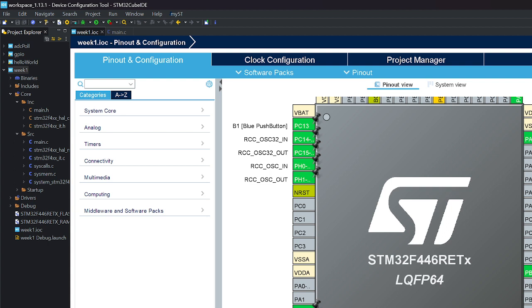One of the nice things about naming them is that in your code you reference them by the port, red LED GPIO port or red LED pin or what have you. Then if you need to change them around, it just changes the defines in the main.h file to the new places, and all your code stays the same.